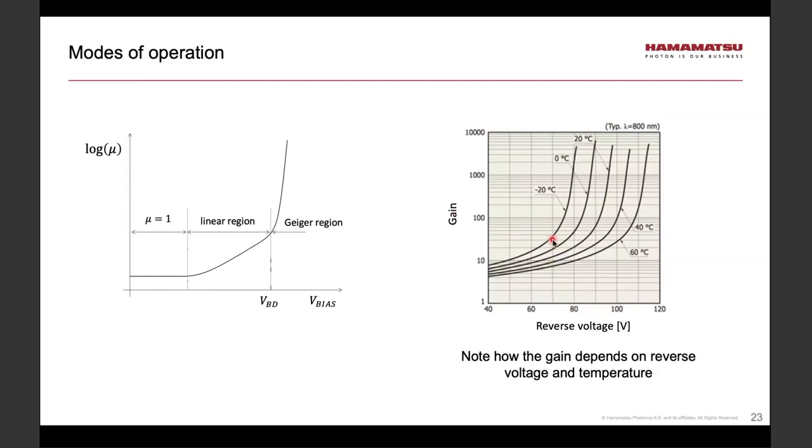Therefore, that change in gain with temperature is going to lead to increased noise, especially if you don't know that temperature changes, then the output is simply going to vary with temperature. To prevent that, one can do two things: either stabilize the temperature or use circuitry known as temperature compensation circuitry, which will keep the gain fixed even though temperature changes.